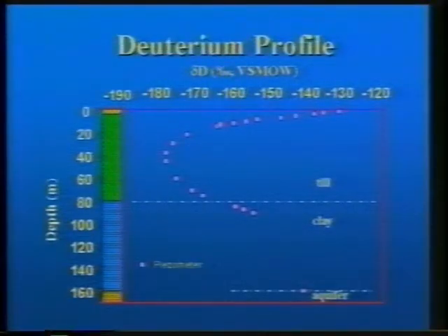First thing we did was, of all these water samples we collected, we plotted deuterium from the piezometers with depth. And these are mean numbers. In the aquitard material, the size of the dot hides the error bar. So we have very tight control, invariant again with time with regard to these isotopes. In the oxidized zone, the upper few data points, the error bars are quite large because of the dynamic flow in this system between spring and summer.